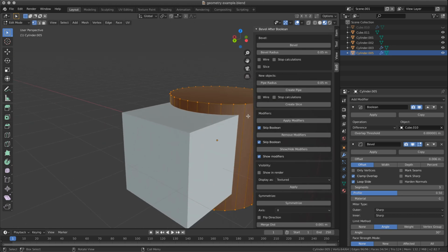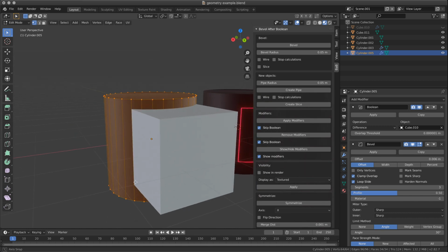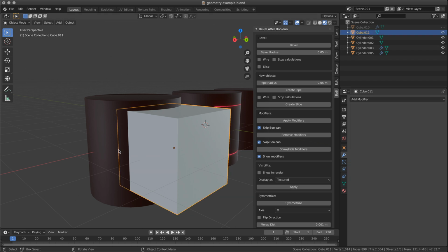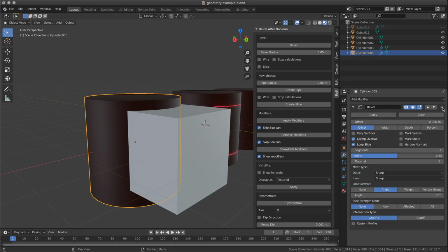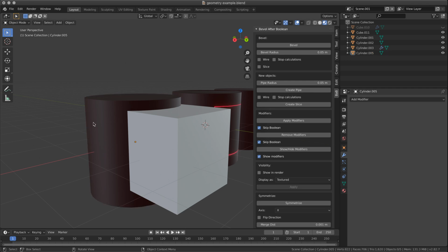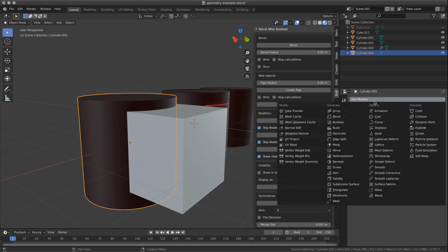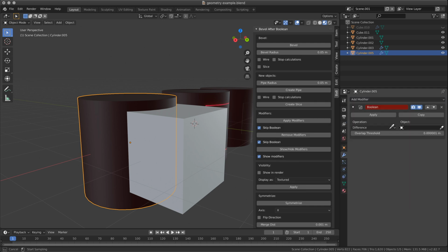You see here I will have a cut in the middle of a face, and here very close to an edge, which may create some problem, and that's exactly what I'm looking for. I'm not going to use the Bool Tool now because I don't want to introduce too many complications. Select the first object, Boolean.